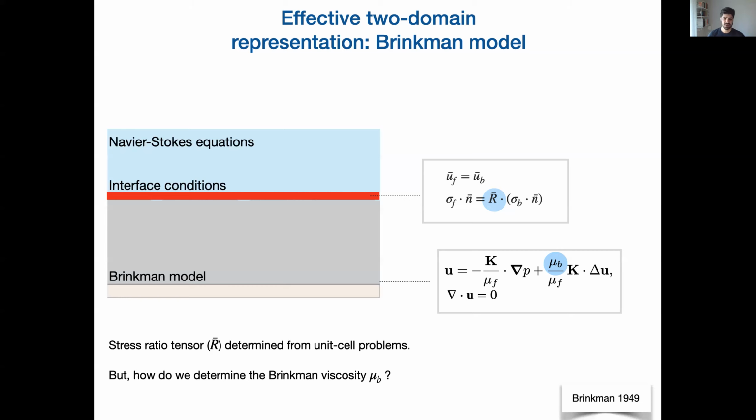Another thing that should be mentioned here is that classically a Brinkman model is mathematically perhaps not asymptotically consistent. It can be shown in certain circumstances to be a higher order correction to the Darcy term. So this term is really relevant if you have very, very sparse inclusions in your porous material. Nevertheless, Brinkman is used even for other solid ratios because of the simpler interface conditions which you have.